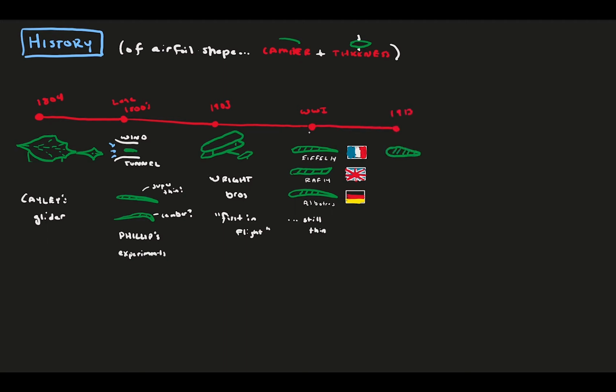And then, Prandtl came along and designed the Göttingen 298, a thick airfoil with absolutely superior performance. Once it found an aircraft in World War I, its capability for high lift meant better takeoff and landing characteristics as well as maneuvering in flight. It was so dominant that turning over the aircraft with the Göttingen foil was explicitly part of the armistice that ended the war.